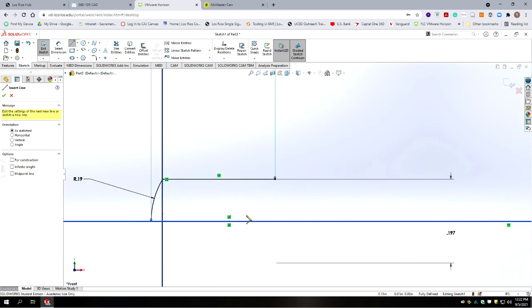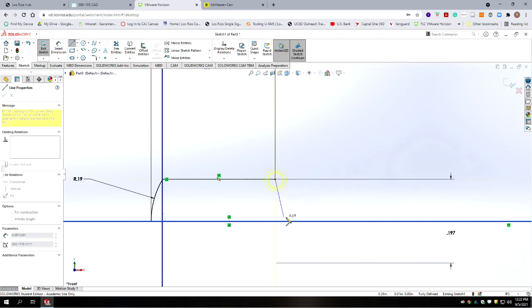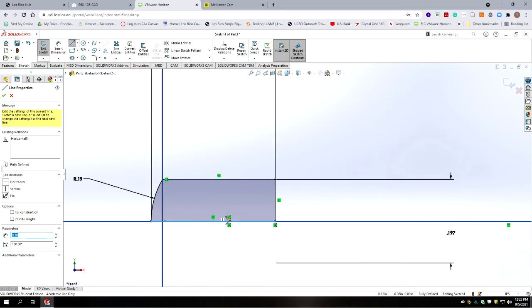Now in this case we're making a complete solid, so we need to enclose our solid to have two more solid lines. Now you can in SolidWorks use the second line I just drew as your revolution edge. Doesn't have to be center line, but I believe for this dimensioning tool it does have to be a center line there present for that associativity.